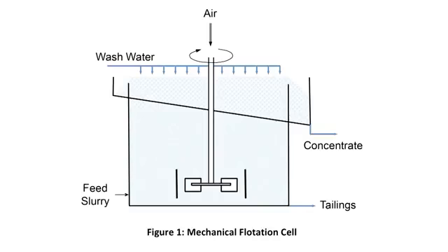There are four basic types of flotation cells: mechanical, column, Jamison, and reflux flotation cells, and there are many variations on these basic themes. We'll have a look at the simplest of these, the mechanical flotation cell. Mechanical flotation cells consist of a stirred tank. Air is sucked in via a central motor shaft, and the spinning impeller acts to break the gas into fine bubbles, as well as to keep the solid particles suspended.